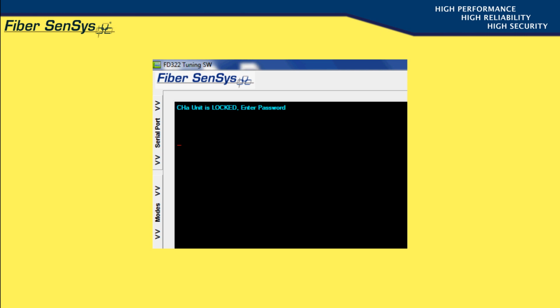To measure the loss or calibrate the unit, access the calibrate menu and type ML and enter. If you respond with Y when asked, "Are you sure?" the display shows the last measured loss value, and at that point you can perform the measurement and calibration processes. Again, this procedure is explained in a video segment that is shown in the calibration and tuning section of this training program.